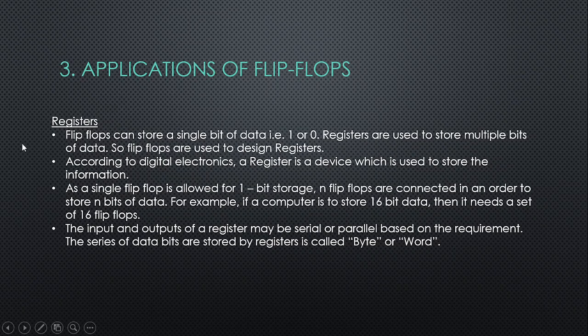Next, application: registers. Flip-flops can store a single bit of data. So registers are used to store multiple bits of this data. So flip-flops are used to design registers. Again, this is another application. According to digital electronics, a register is a device which is used to store the information given. As a single flip-flop is allowed for 1-bit storage, n flip-flops are connected in an order to store n bits of data. For example, if a computer is to store 16-bit data, then it needs a set of 16 flip-flops. So n flip-flops in order to store n bits of data.